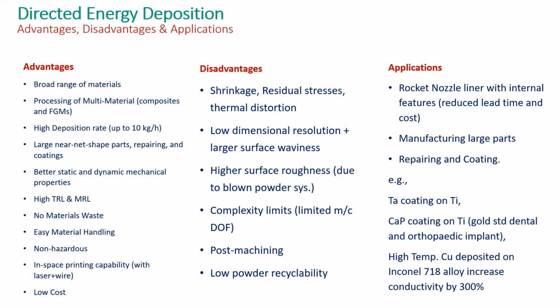In a similar way, we can coat calcium phosphate on the titanium component, or high temperature copper on Inconel 718 kind of alloys. So this can be achieved by this DED technique. These are several applications of the DED technique.